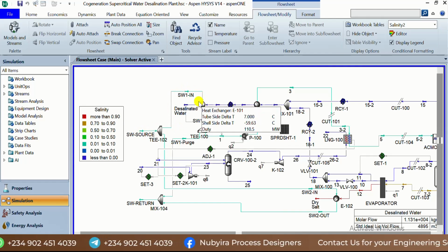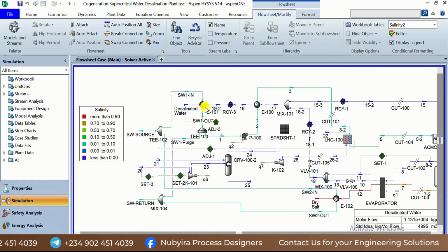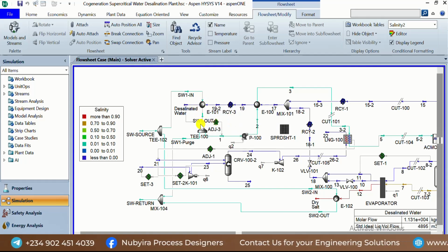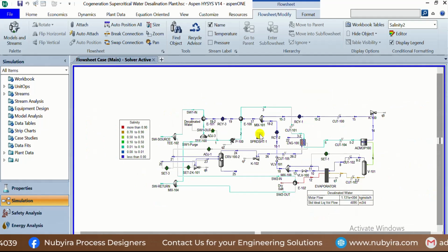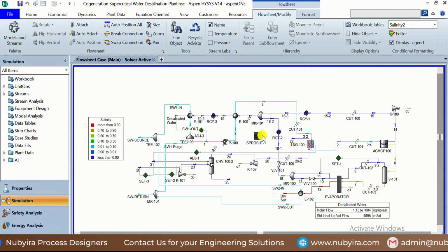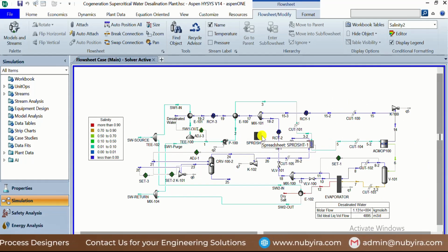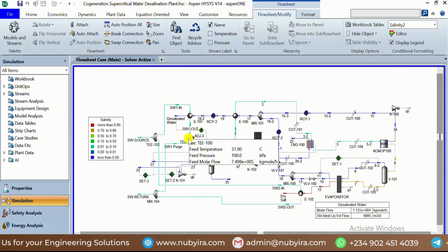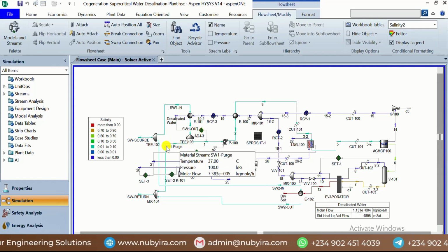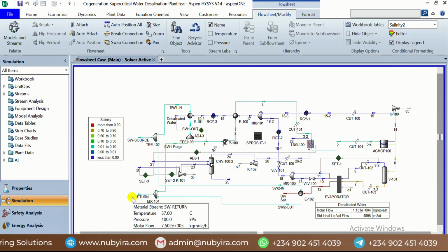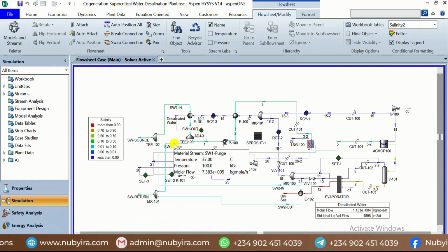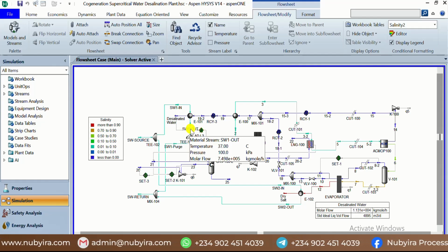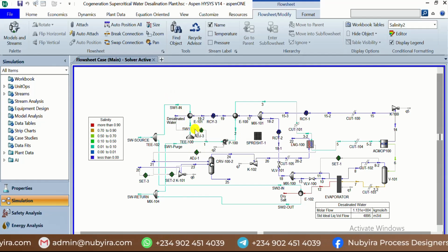One is used to cool down the desalination water, because this kind of plant is a power plant and it needs a lot of cooling. So you'll be taking a lot of water in, and you split it into two. One is returned back to the sea, and I make sure that the temperature difference of the water is not too large. You can see from 30 to 37.